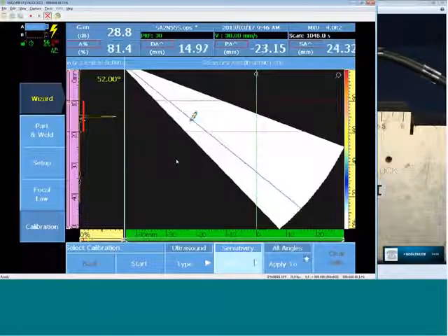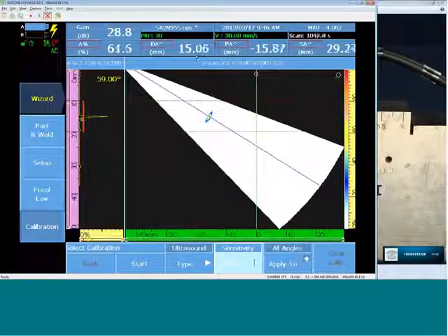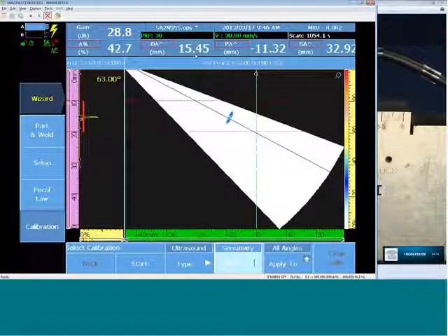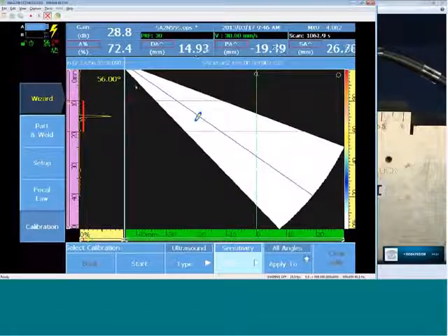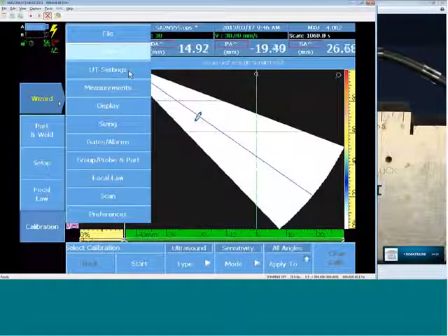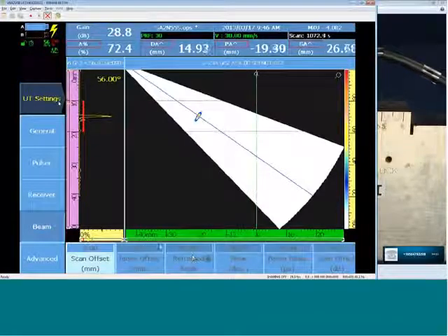What that tells us is that the software under Beam has calculated from the wizard our wedge delay correctly. I can perform the wedge delay function, maybe tweak it a little bit, but in accordance with the codes, in accordance with a conventional UT, my ability to verify this position prior to calibration verifies both the velocity of the wedge and the wedge delay that was calculated by the calculator. So we want to be careful not to downgrade our calibration with a large side drilled hole or by trying to fix an angle error or velocity error that's not really our problem.